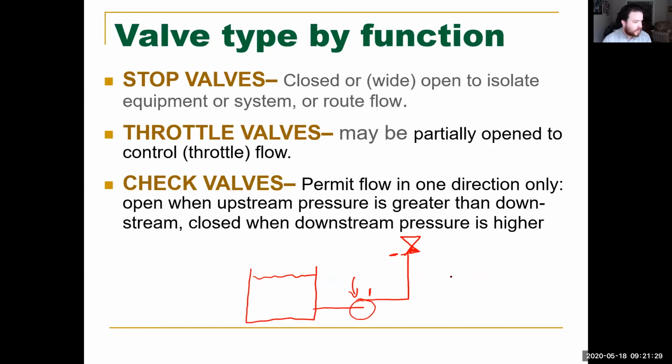When the pump turns off, all of this fluid that's in this pipe, if this check valve wasn't there, would return back into the pump, and the pump would turn back on because now there's fluid inside the pump, and then it would pump the fluid back up until it ran out of fluid, and then there's no more fluid, so the pump turns off, and it just keeps cycling like that.